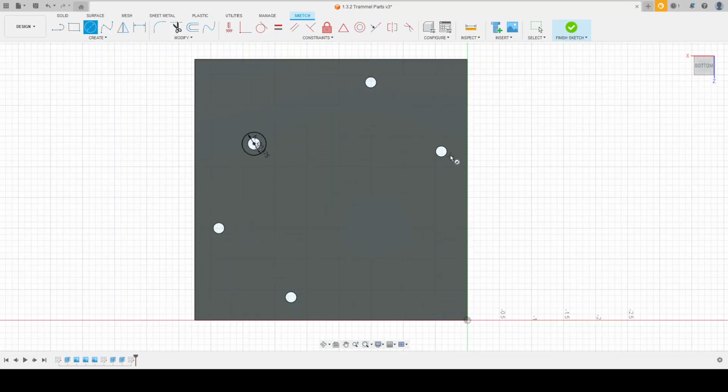These other positions are going to be a bit more tricky. There are a few different ways to create polygons, which is what we want to do here. Depending on how you measured those hexagons, there are some different options. There are inscribed polygons, which means they fit inside of a circle. So if you measured opposite points of the hexagon, you would use this. There are circumscribed polygons, which means they're measuring from the flat edge to the flat edge. So if you measured across the hexagons, you would use this polygon.